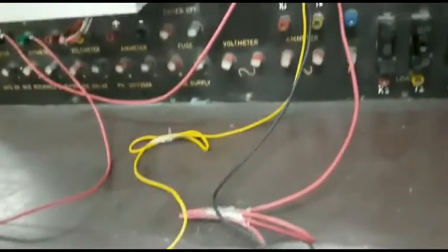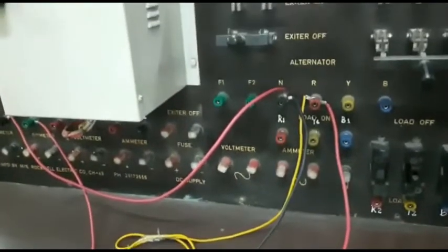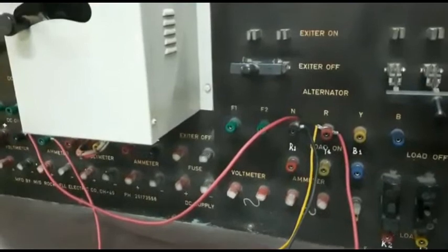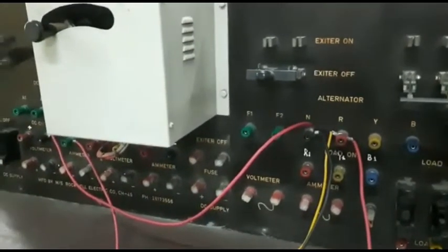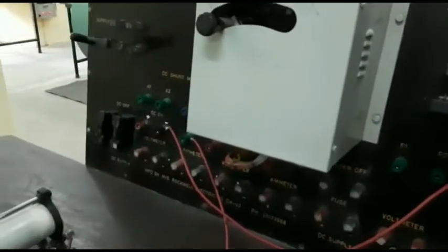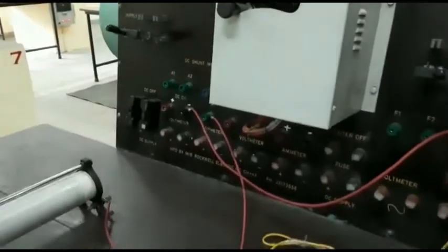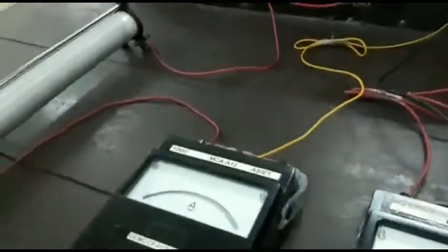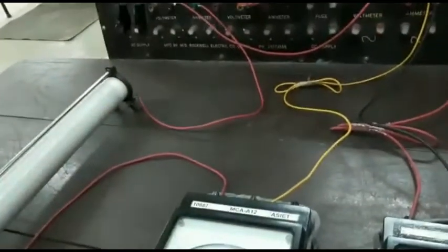But here, an alternator is an AC generator, so we are dealing with an AC supply, and we need to measure AC resistance. So RDC, if you calculate, we have to multiply it by 1.6 and you will get RAC. Okay, and that is how you have to measure RAC. RAC measurement is also involved in this experiment. Okay, and that is the way we have traced the circuit.